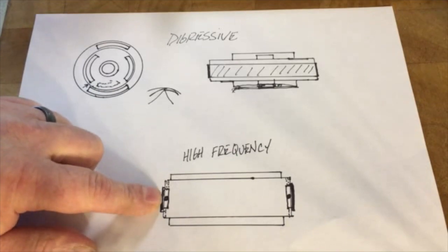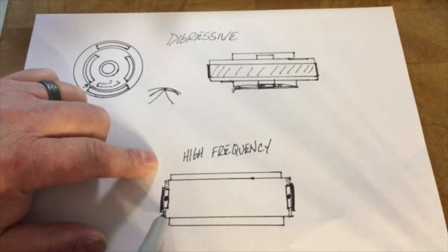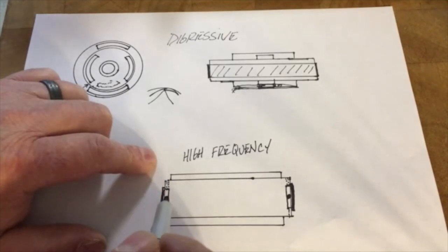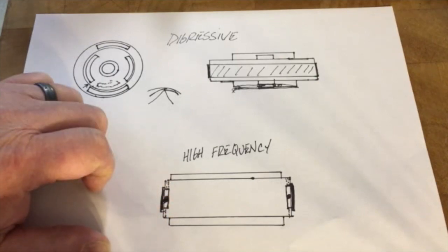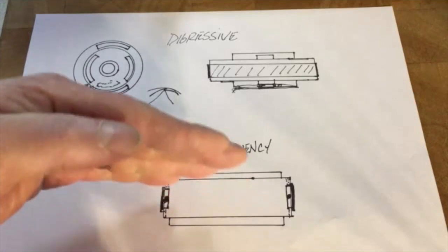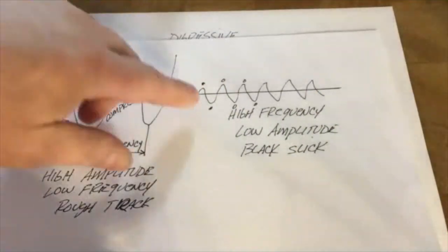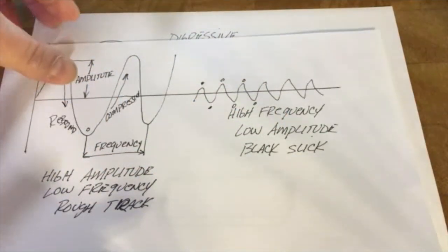The other thing I wanted to talk about is a high frequency piston. I drew a little diagram here. These were little bleed orifices here, and they went from the top and the bottom, and this O-ring was smaller than the slot it sat in. So as this piston would go up and down on a high frequency track, similar to this, it's traveling with a lot of frequency in it.